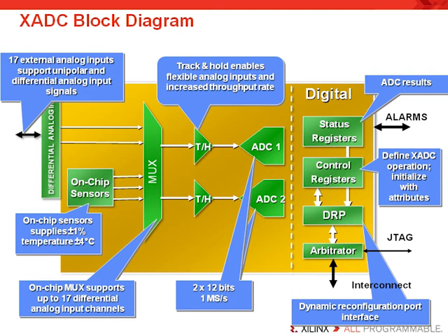The analog input channels are very flexible and support multiple analog input signal types. Now, you can program the input to cope with bipolar or unipolar signals. The analog inputs of the ADC core use the differential sampling scheme to reduce the effects of common mode noise signals. This common mode rejection improves the ADC's performance in noisy digital environments. The differential inputs in the bipolar-unipolar modes provide support for a wide number of sensors. Remember that some analog signal limiting may be necessary to protect the analog inputs on the FPGA.